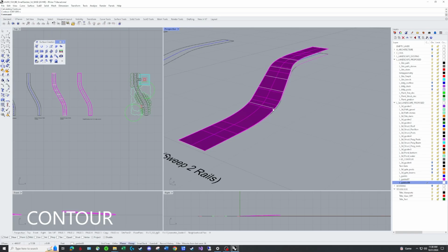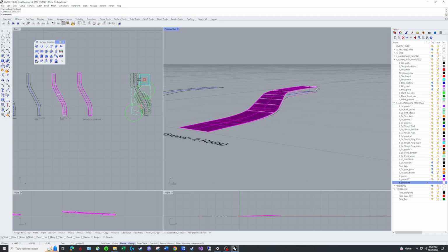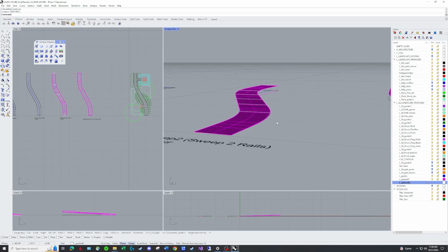And so it's just exactly what I suspected from my visual observation, that the path goes out very flat. You have this parabolic curve ascending in the middle, and then it's flat here. If you wanted to do this as a design move, you can. But I think the point is we need to be controlling this, not letting the computer just choose a not correctly graded pathway on our own. We intended it to be uniform.